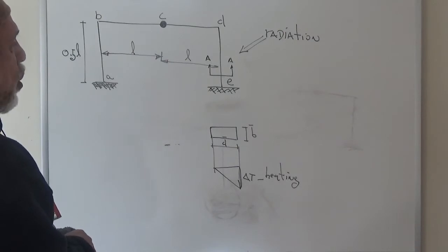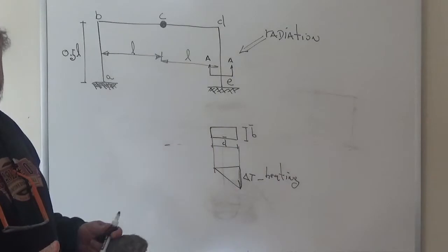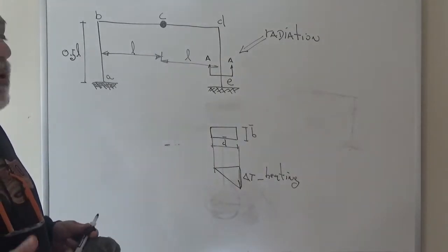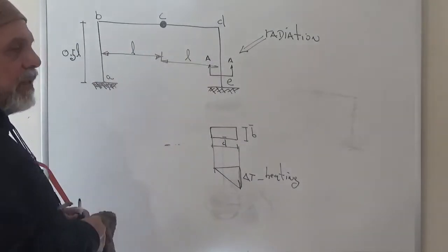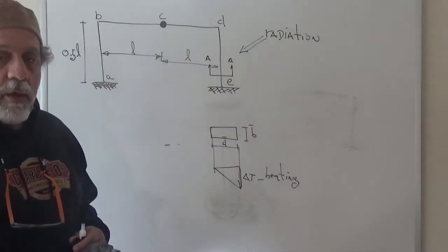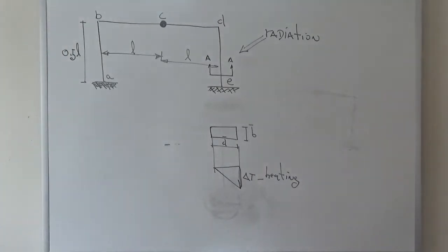We want to know what are the moments, shears, stresses everywhere. We would like to know everything about what is happening on the structure, about what that effect does to the structure. By the way, if the structure is statically determinate, in previous lectures, before we started with indeterminate structures, we calculated deformations due to temperature, never calculated moments and shears.